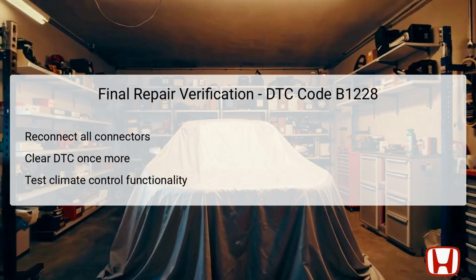Once all repair steps have been completed, it is imperative to verify that the repair was effective. Begin by reconnecting all connectors that were previously disconnected during the diagnostic process. This step ensures that the climate control unit is re-established and can receive accurate signals from the outside air temperature sensor. After reconnecting, use the HDS to clear any lingering DTCs.